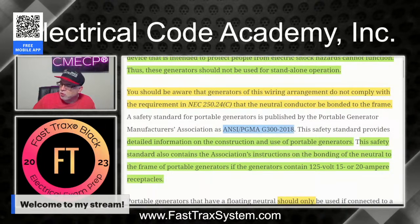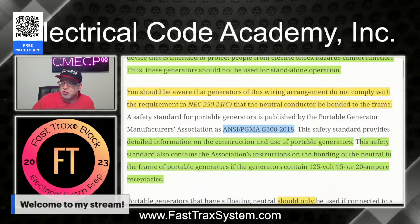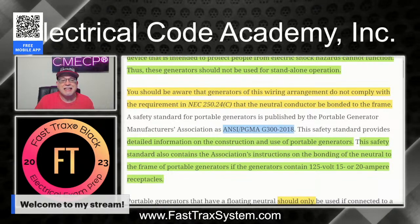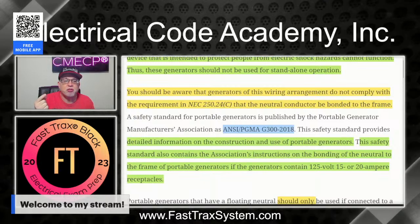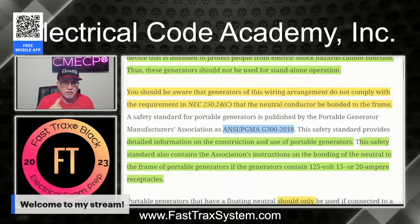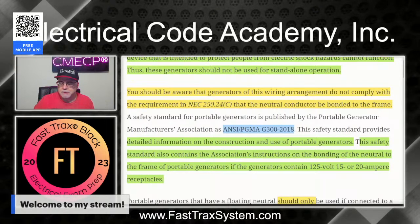And it's also going to tell you the instructions on bonding the neutral to the frame if the generator has 15 or 20 amp, 125 volt receptacles. Then it's going to say, hey, if you've got these receptacles, guess what? I'm going to need you to bond the neutral to the frame of this generator. Okay? So that's where you're going to get all those instructions.